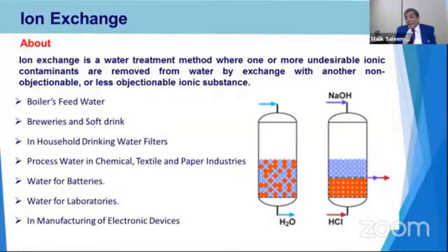One participant has asked what is the freeboard. If you are watching this picture, this is the free area. This is the bed depth of the resin. When we backwash, we give water from the back to expand this bed, and then we drain this water while doing the backwash.